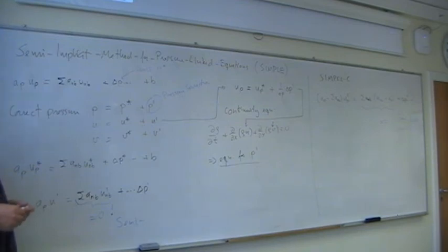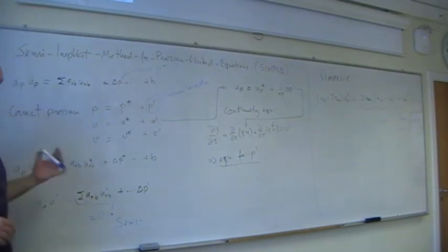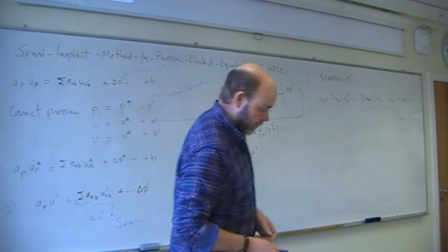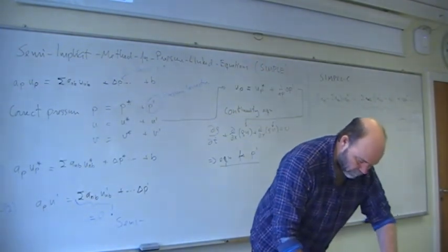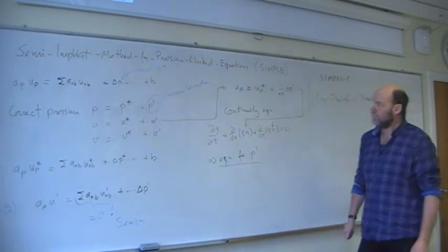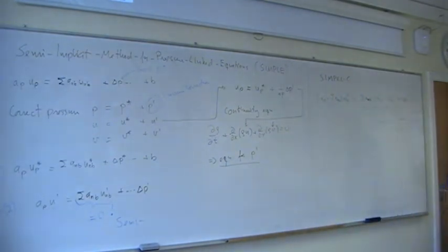And it's possible here, if you go through it with a rectangular cell system, don't use triangles, but just use straight rectangles, uniform mesh, you will see that this method is identical to the projection method that we had with finite difference. It's exactly the same. So of course, they are in the same family. Any questions to this one?